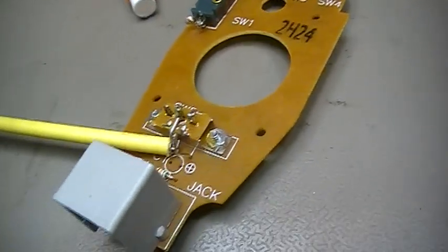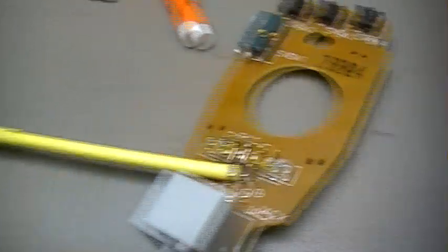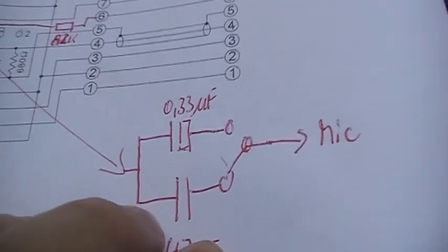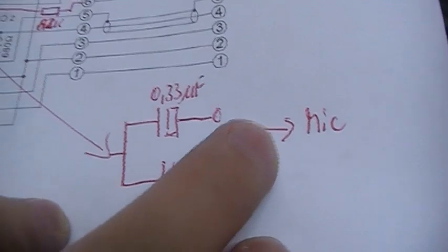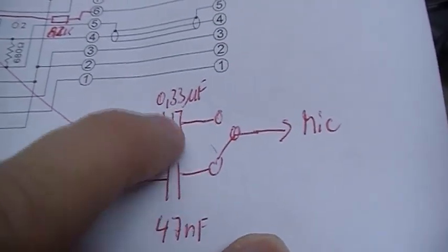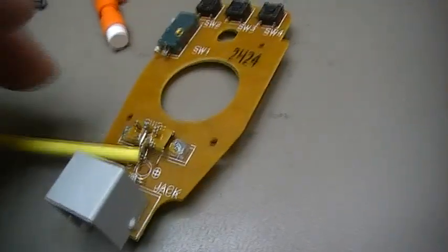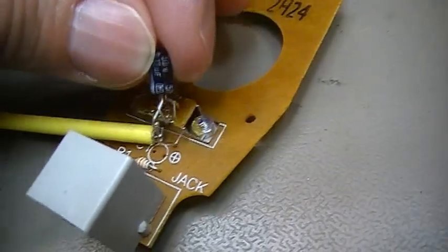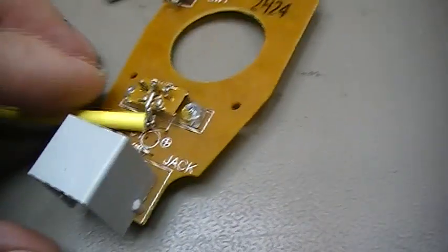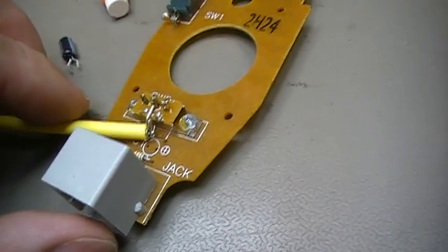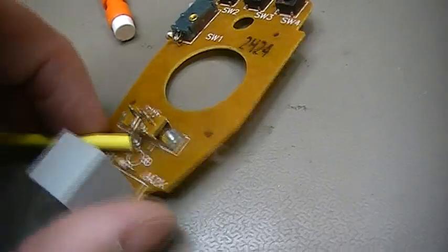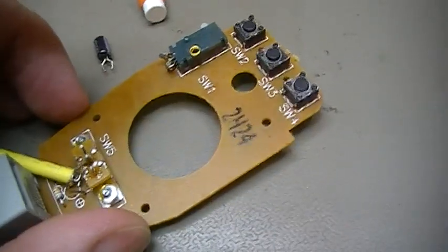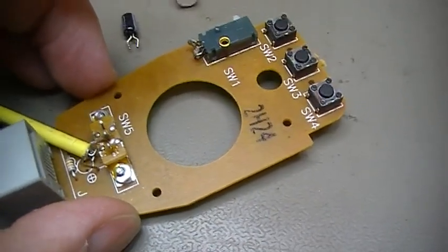That is the way how we can now fit in this solution, so that we are able to switch between both conditions, and that is what we are going for. So we put this inside together with the 47 nanofarad, and then we have to add our resistor to get the 5 volt to the capsule. Yeah, and then we will see whether it works or not.